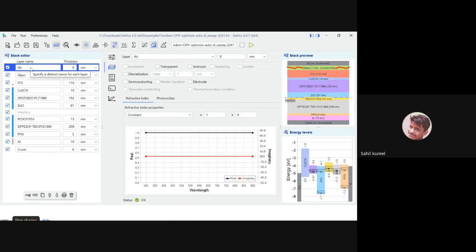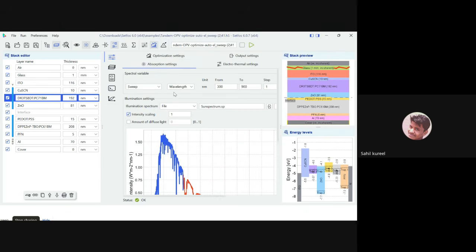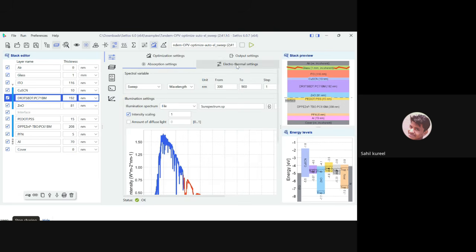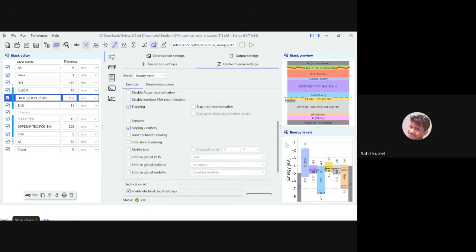How you can optimize your structure when you activate absorption and depth diffusion. You can follow that same layer stack and create it. Then you can set the thickness. One by one you can provide the optical data, then you can provide the electrical data. Simple steps. You can activate the absorption parameters and then provide that value. And after this, you can give the electrical data in here. You can provide that value.